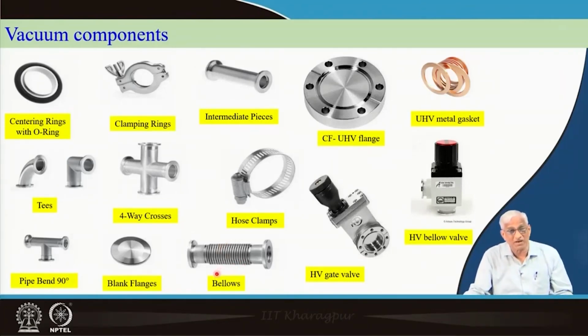In the initial days of vacuum technology, these were not there. They had a lot of tough time, and you cannot introduce rubber pipes, because they will degas, and you need very high quality brazing here, otherwise they will leak. You cannot have a flexible thing which is leaky. And this is the gate wall, for example. Control valves are there, like bellow valves. The bellow will isolate vacuum from the atmosphere. So, all these things over a period of time they have developed, and today they are standardized.